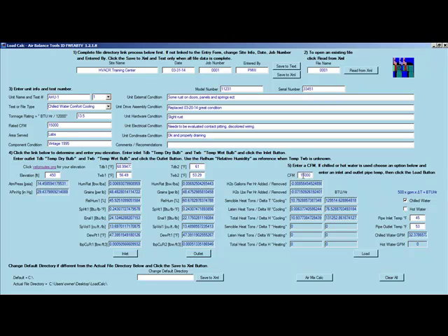This is a 15,000 CFM air handler. We hit our load calc. This is a chilled water coil. So at this point we would only be flowing 32.4 GPM through this chilled water coil, and our BTU transfer would be about 10.7 or 10.8 tons, and this is a 13.5 ton air handler.